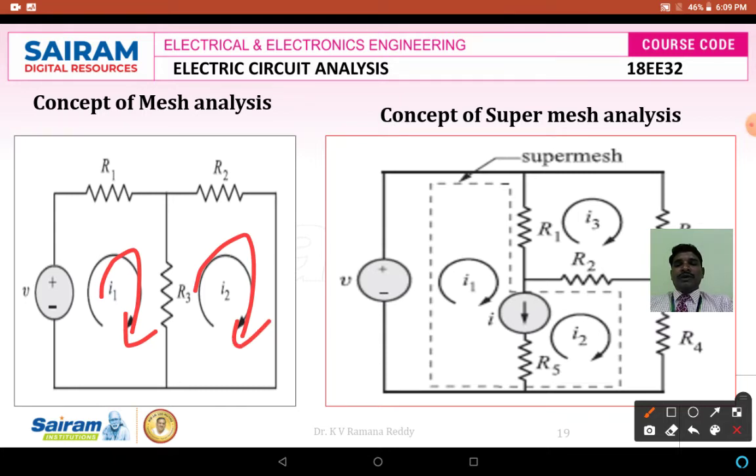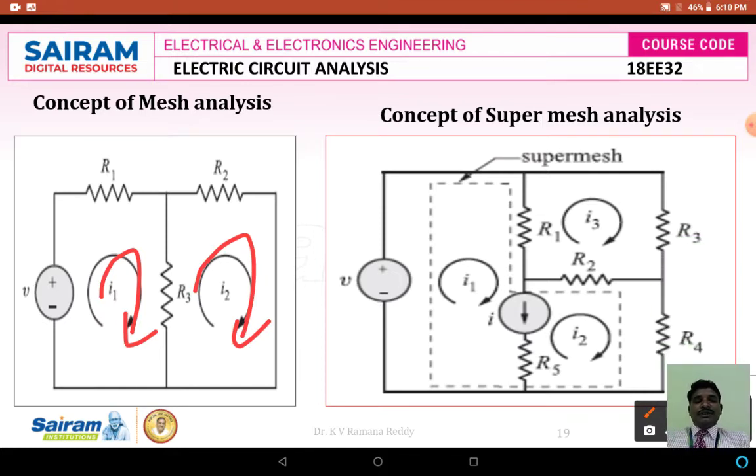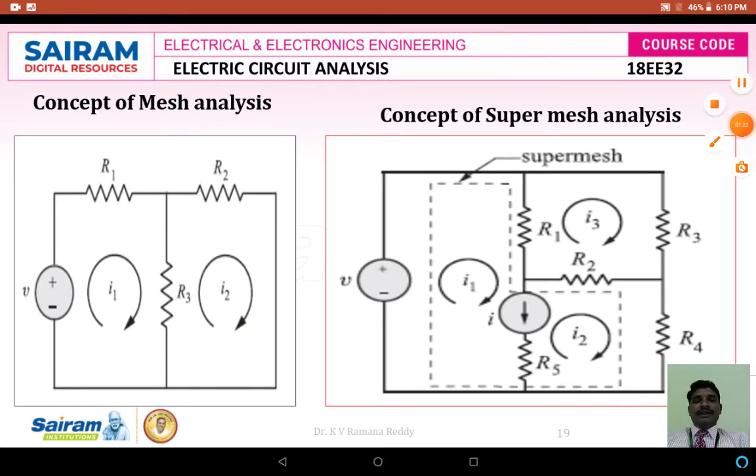So this is the way we approach mesh analysis to find the unknown currents in those loops, and the branch currents we can find out. The number of mesh currents is equal to the number of mesh loops in the concept of mesh analysis, and the direction of currents we can choose as we wish. Then whenever a current source is located between the boundaries of two meshes, it is difficult to analyze the circuit. In that case we apply super mesh analysis.